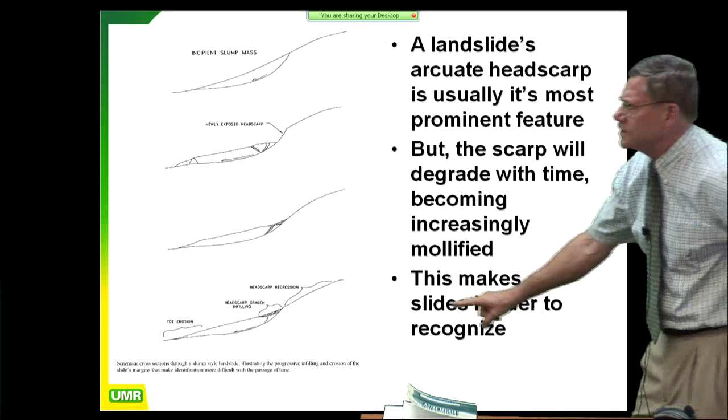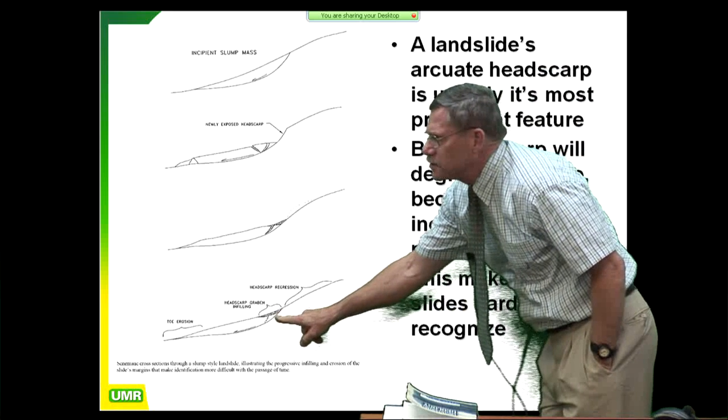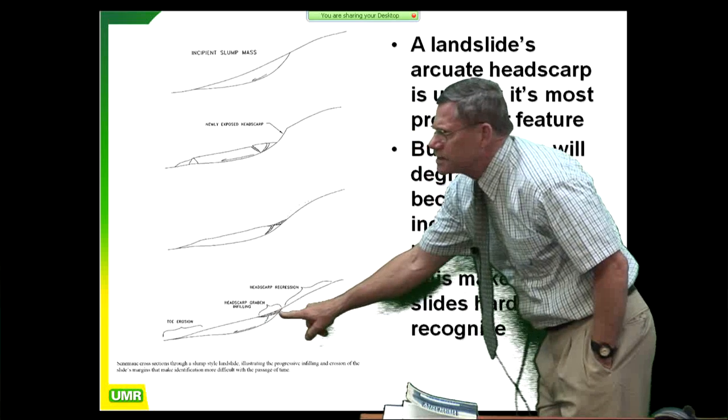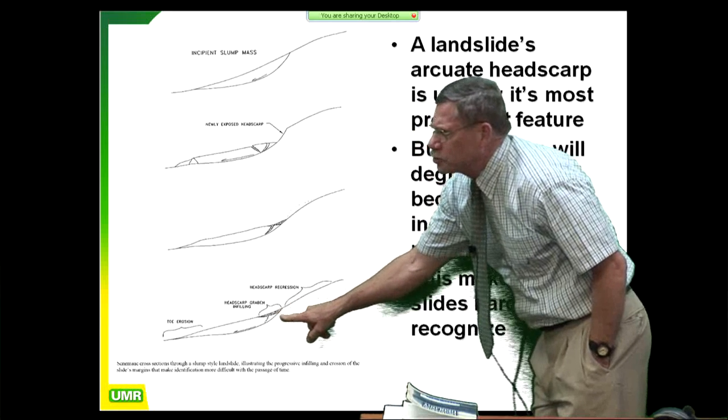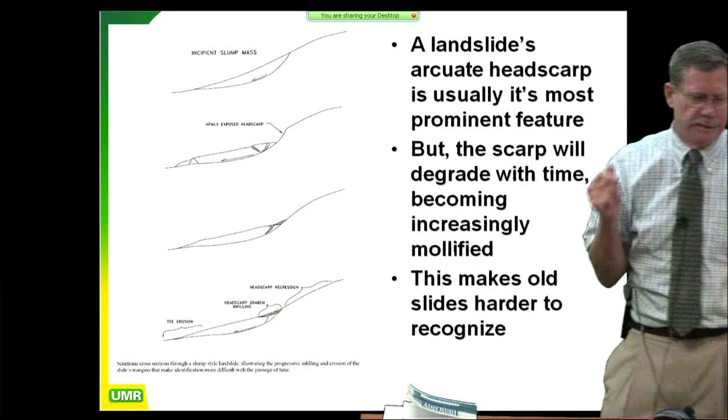Now, one of the things you want to notice there is you have all this very low density soil, colluvium, which recently washed into that scarp. If you go out there and you trench this, it'll become patently obvious to you pretty quickly if you're looking for it.